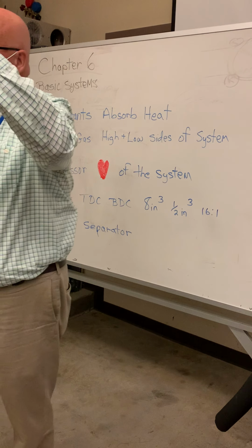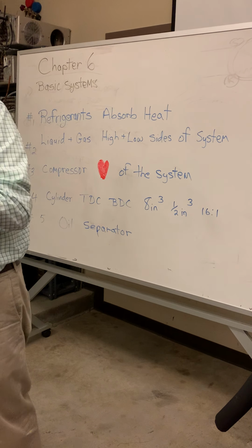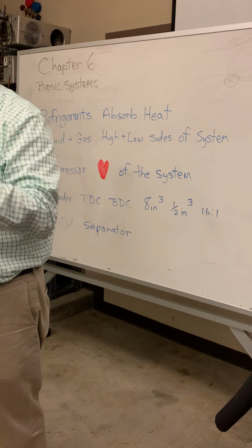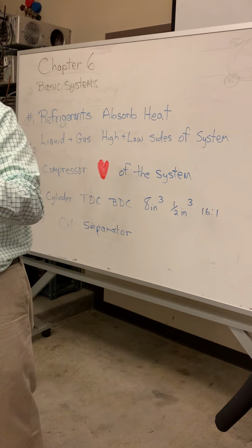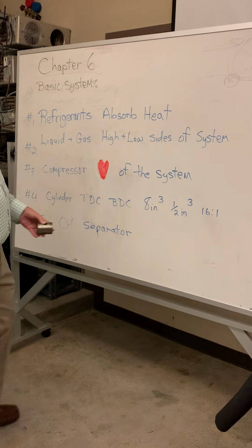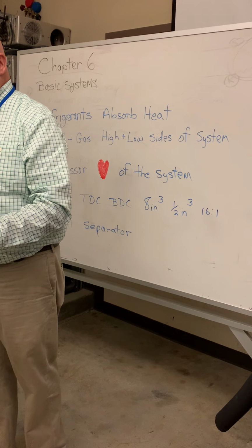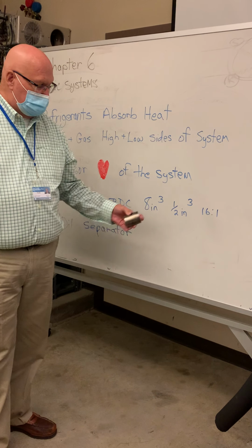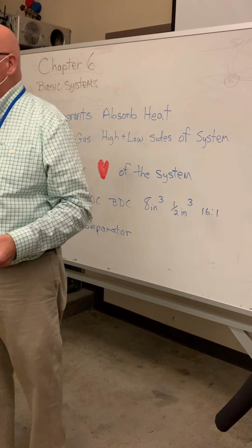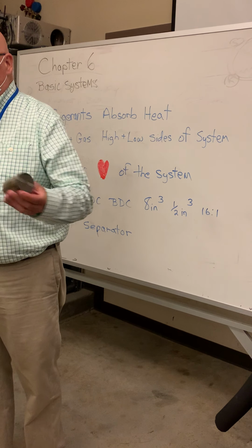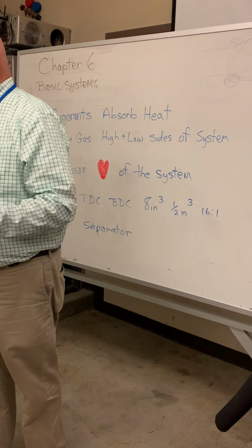And when this piston is at BDC, bottom dead center, if you look in your textbook, it gives you the volume of that space. In the textbook example, when it is at bottom dead center, that means it's down as far into the cylinder as it can go, and you find that it is 8 inches, with that superscripted 3, that means cubed, because that's how we measure volume, in cubic feet, cubic inches.